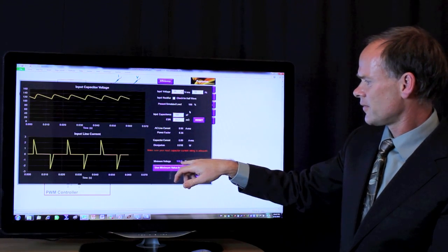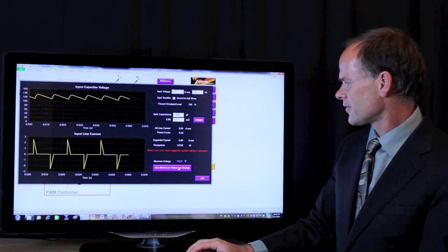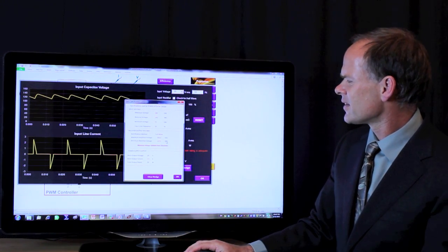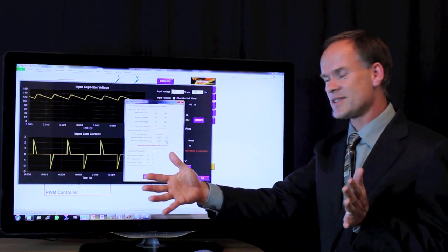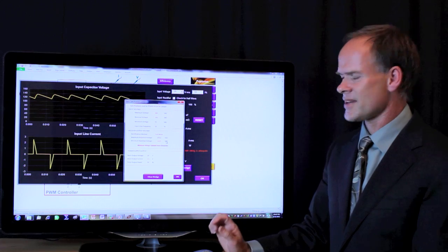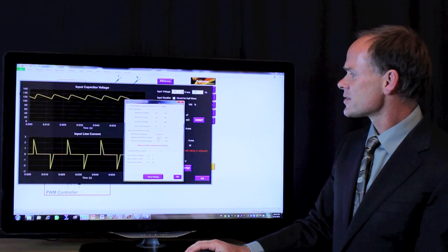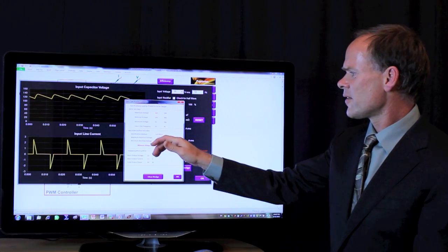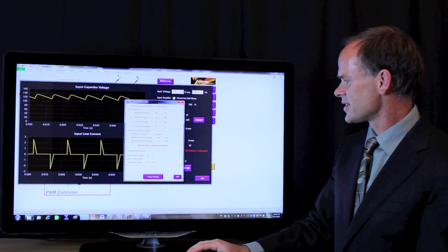And that's 112 volts DC here. What I really should do now is click on this button right here and use that minimum value for your design. By simulating the input bridge, I now know my true input DC range, which is going to be 112 volts DC up to 373 volts DC for a 264 volt AC line. So now it's going to redesign the capacitor, the inductor, the control loop, etc. for that minimum input voltage that comes from the simulation of the AC rectifier.